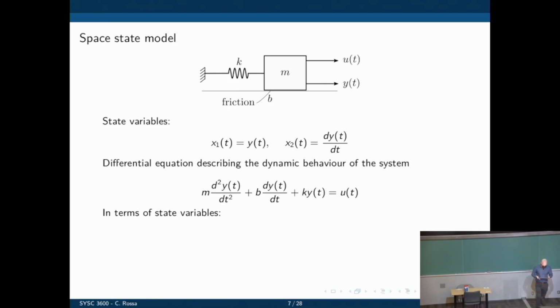So now let's rewrite this equation using our state variables. Remember that the objective is to convert these high order differential equations into first order differential equations. So when you now rewrite the equations, always use the lowest available derivative. The lowest available derivative. You understand what I mean? We'll see it when we do this example.